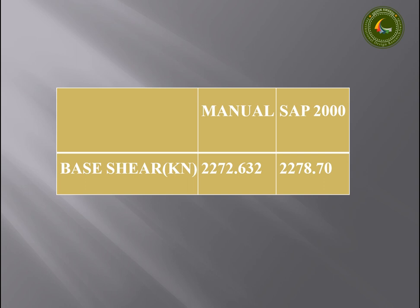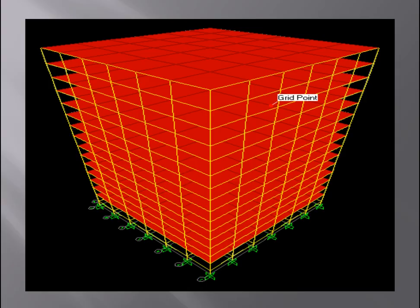So here are the results that we have got. From manual calculation, we got a result of 2272.63 as our base shear, which is in kilonewtons. Similarly, we got an almost similar value when analyzed with the help of the software, which is 2278. So we can finally conclude that our software gives somewhat better results, and it also reduces the time period.